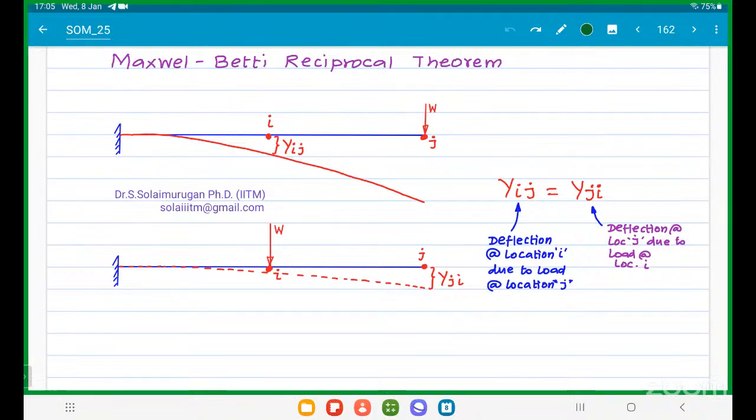You have written many exams also. Energy stored in the material when it is loaded up to the proportional limit. All of our formulas are valid up to the proportional limit: Young's modulus, bulk modulus, shear modulus, Poisson's ratio, strain energy, Hooke's law. Strain energy is nothing but energy stored in the material when it is loaded up to the proportional limit. Strain energy is 100% recoverable energy.